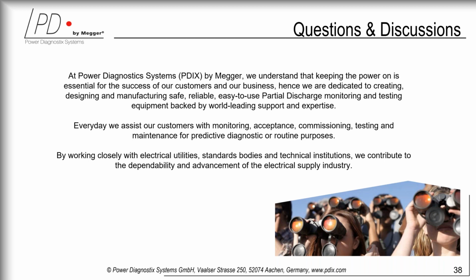All right. I'm going to send a question over to Charles to shake things up. Charles, how do we differentiate whether PD is from a bushing or a winding? So Marcus had touched on this a little bit before, and basically you can tell by the pulse shape analysis. As Marcus said, if you have PD from the bushing, it'll look a lot like the calibrating signal. You can also tell by testing at a bushing whether or not it's coming from that bushing. Obviously, if you test from the other, you're not going to get the same pulse shape or intensity.